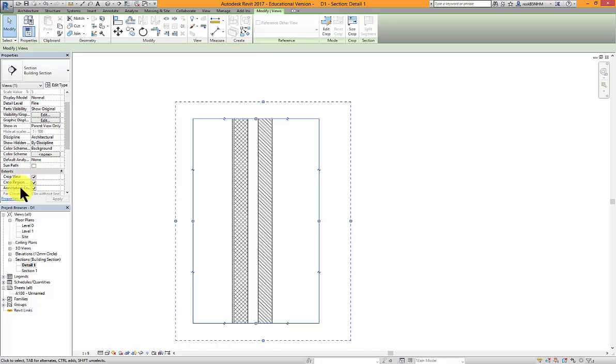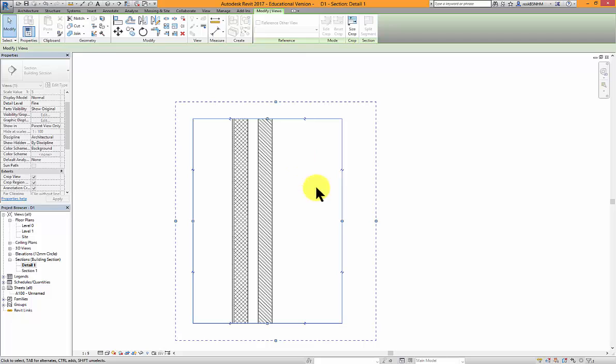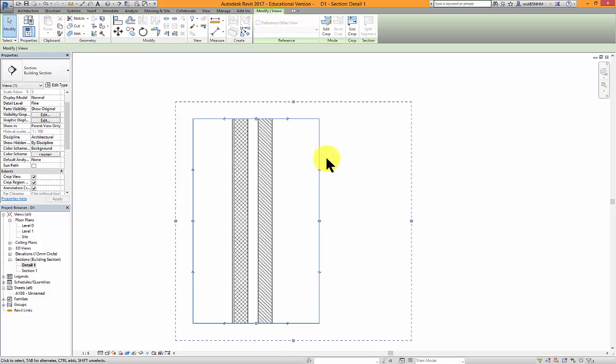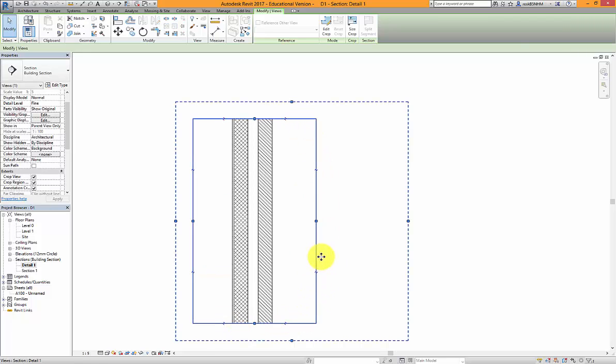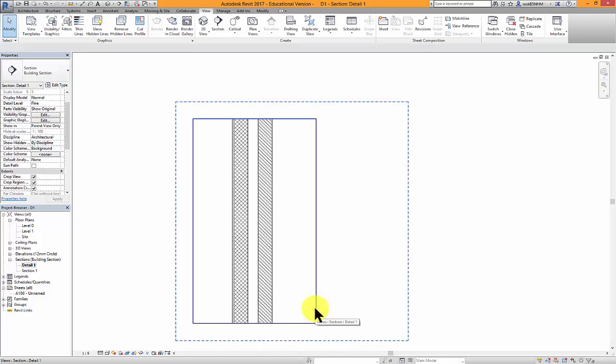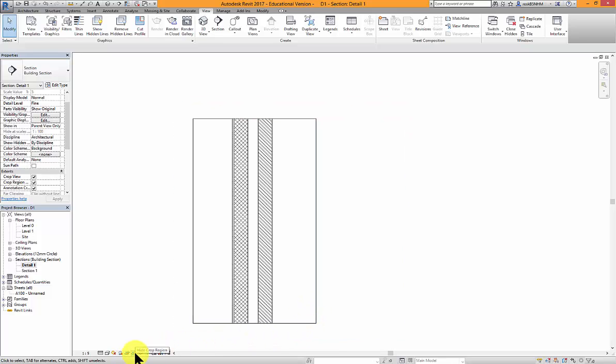That's the annotation crop region, as I'm going to put some text here. So we can actually keep the callout here, but just for our text, I would like to extend this area here. So if we put some text, it's going to be visible even though the crop region finished here. Now, next, I would like to hide this crop region. So hide crop region.